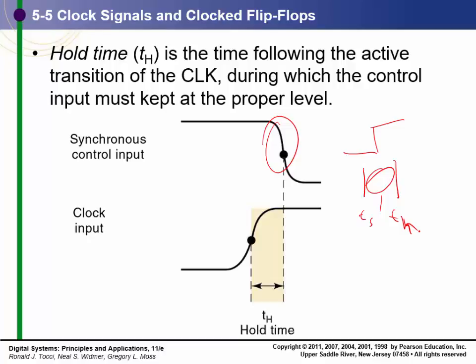As long as we're using inputs that are coming from within the system, that's not a problem. Flip-flop outputs are fine. The Qs are feeding others. They're going through gates and everything's fine. Sometimes we may have to latch some inputs that are coming from the outside world.